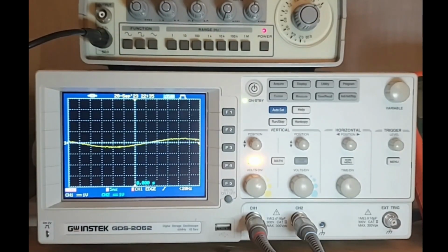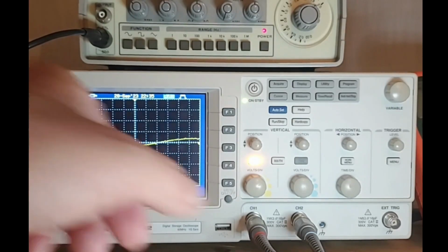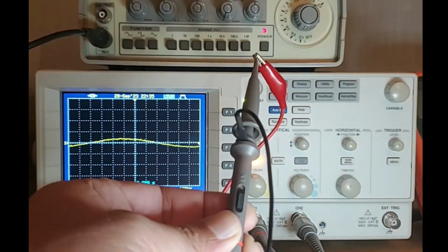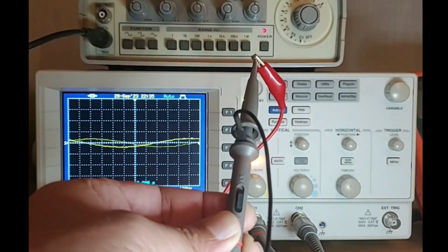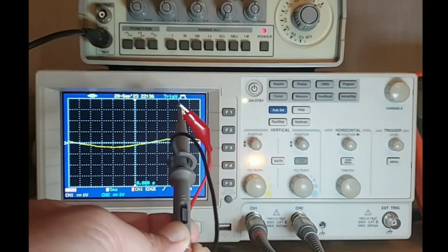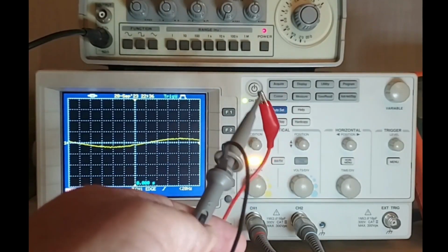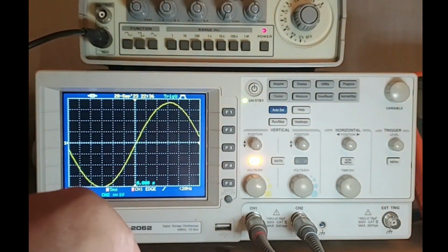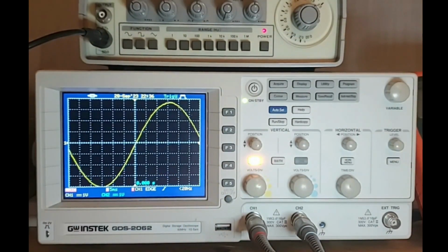but it is not very clear what is happening. So the first thing I think we should do is that I have used a multiply by 10, which means that I'm dividing the signal from the function generator by 10, and then I'm displaying it on the screen. So it looks very small. So I will bring it back to multiply by 1. And now you can see that this is the actual waveform that the function generator is producing, which is a little bit too large. It is going out of the screen.